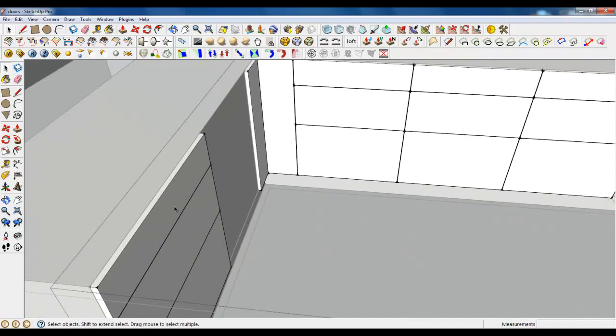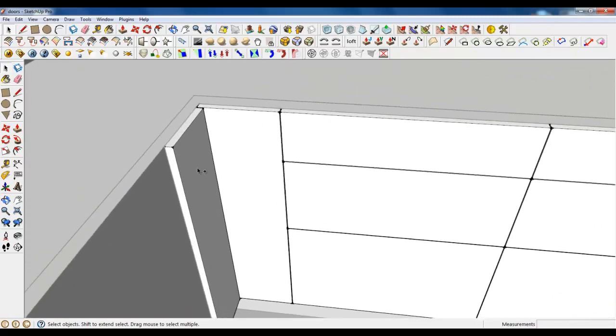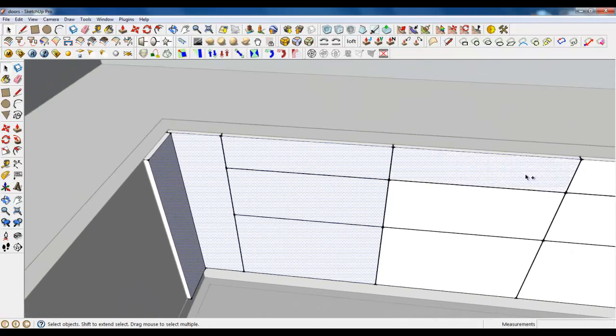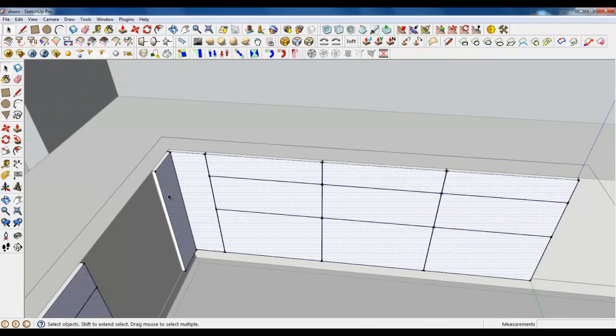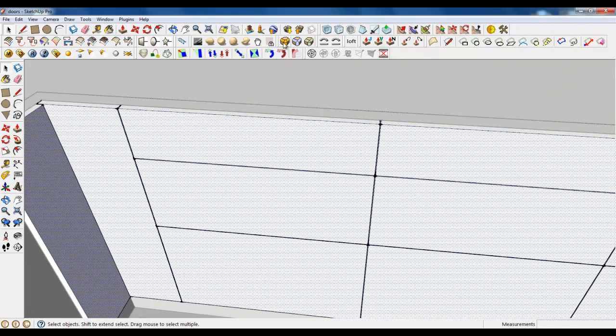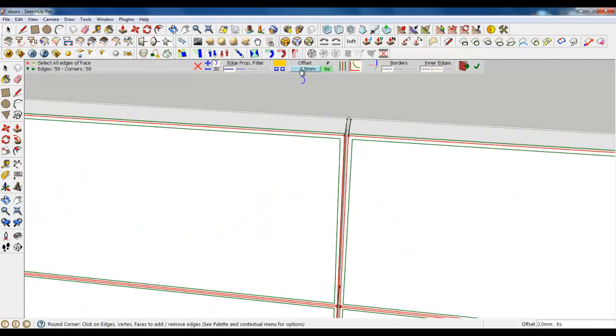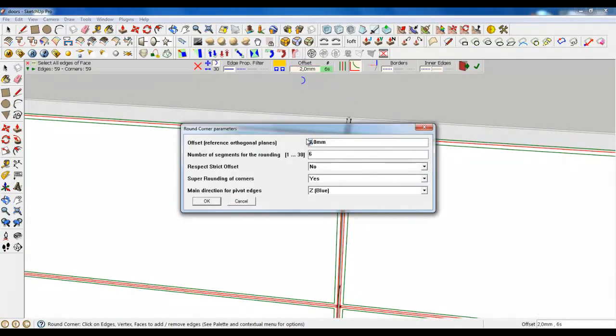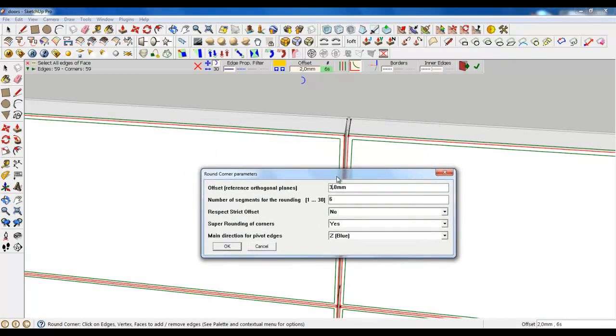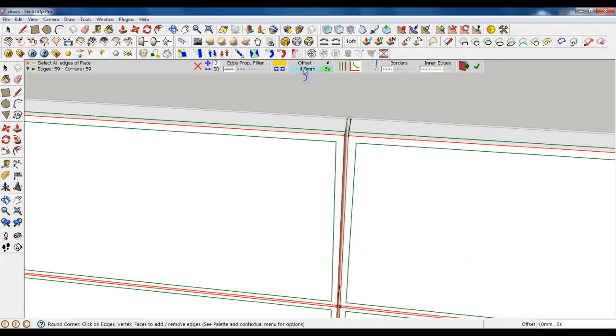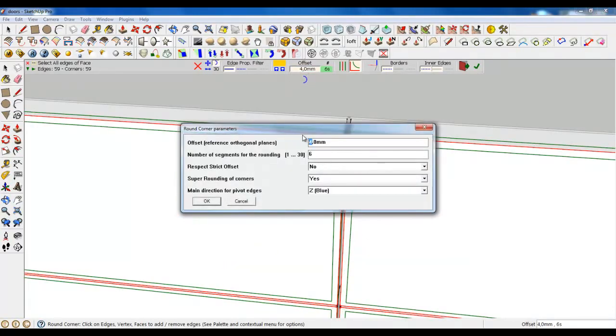It's perfect now. And we need some details, so let's add. Select all the planes and choose round corners in 3D. Make 3, maybe 4 and 6 segments. Yeah, it's a little bit too much, so let's type in 3.